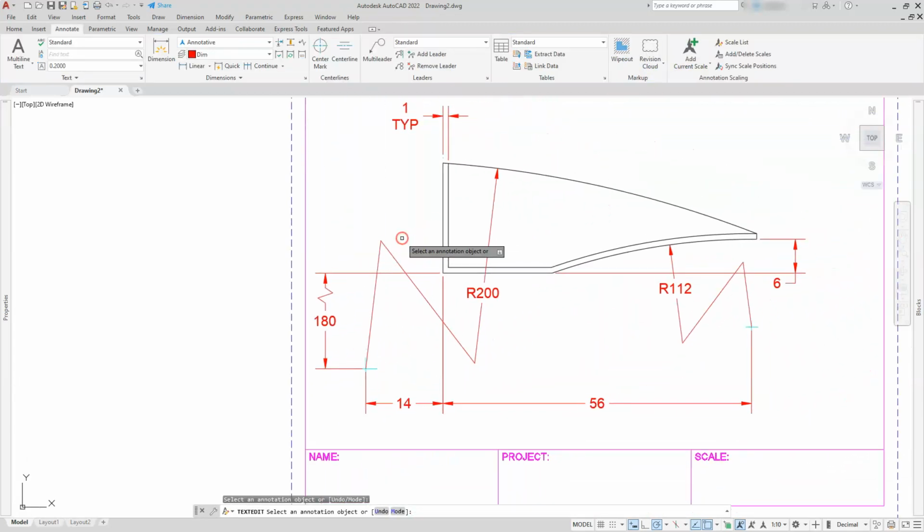Okay, so the last thing that I'm going to show you about these jog dimensions is that sometimes they look a little bit bigger, and you can't control too much of that part of it, but you can control the angle of it or how you can kind of view it. So by default, these are set at 45 degrees, and that number is going to be located inside of your dimensions.